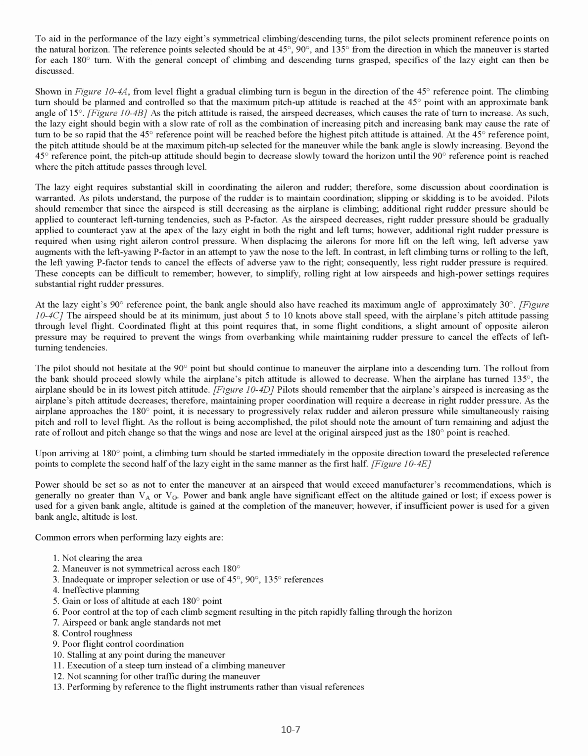Pilots should remember that the airplane's airspeed is increasing as the airplane's pitch attitude decreases, therefore, maintaining proper coordination will require a decrease in right rudder pressure. As the airplane approaches the 180 degrees point, it is necessary to progressively relax rudder and aileron pressure while simultaneously raising pitch and roll to level flight.